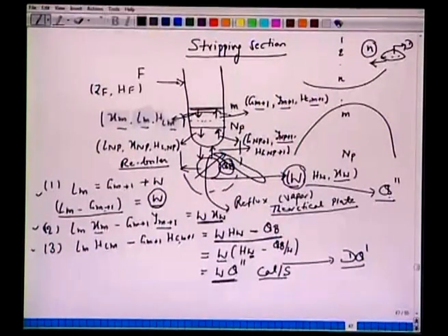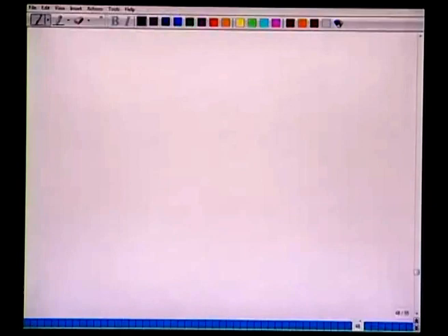So with these three equations we can again simplify, or rearrange, to write Lm over Gm plus 1. It is the same similar expression we obtained for the top column. This would be your internal reflux, if you call it. We had external reflux R; this is like internal reflux, Lm, the liquid molar flow rate which trickles down, to Gm plus 1 at any location, which moves up.